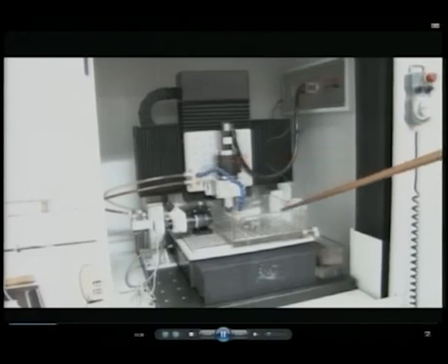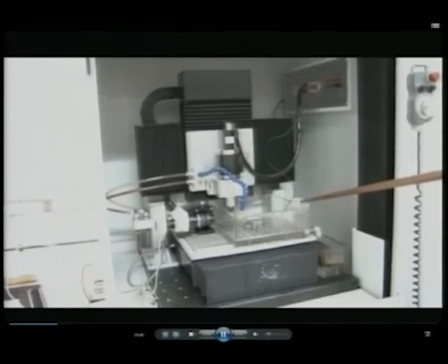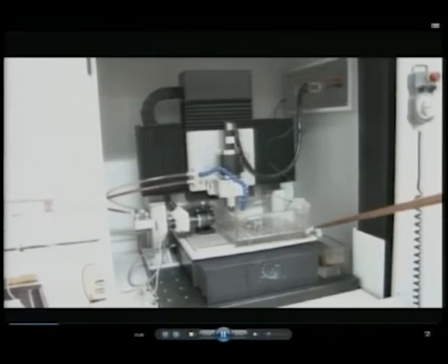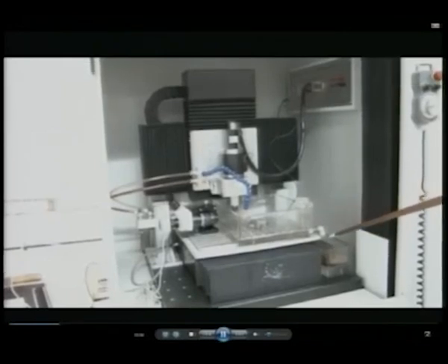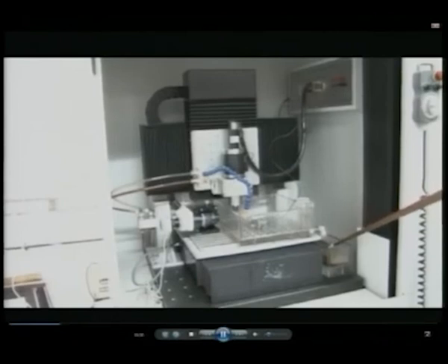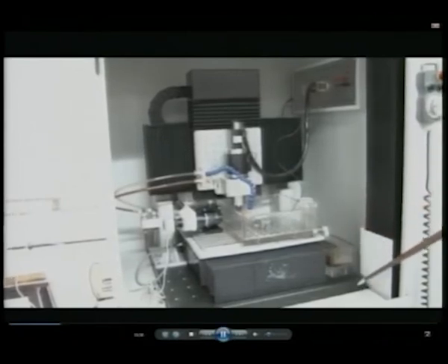The fluid as it enters into the tank will get filled in the tank till a certain level is reached. Once the level is reached, the dielectric overflows through this valve to another tank which contains a filter. All the debris which is formed during the process is filtered in this filter, and the filtered dielectric will enter into the tank which is under the table. In this way, the dielectric is recirculated continuously during the process, ensuring fresh dielectric for the process.